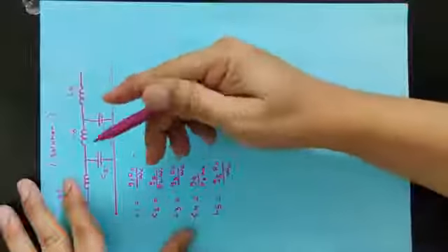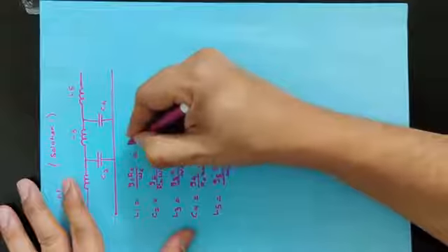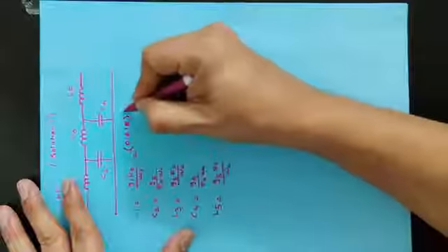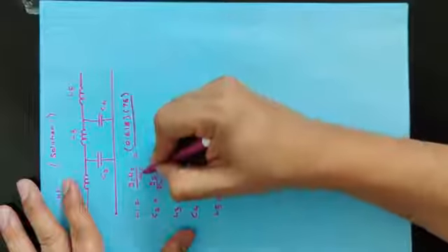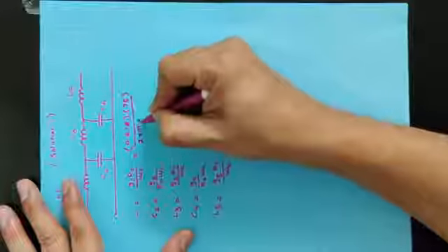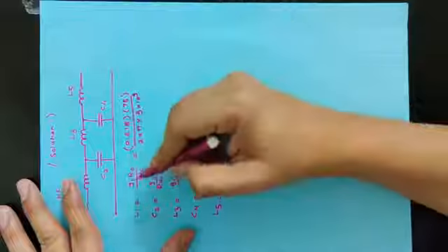R0 they have mentioned as 75 ohm. So I will show the calculation of one of the elements. It will be 0.618 into 75. Now be careful, here they are writing omega c. So it is 2 into pi into fc, and fc is 3 into 10 to the power 9 hertz.